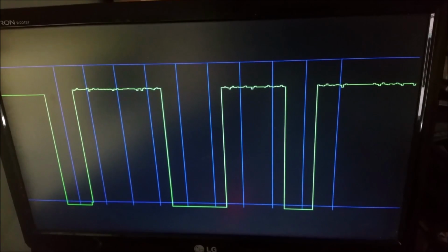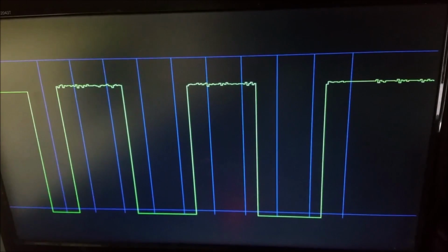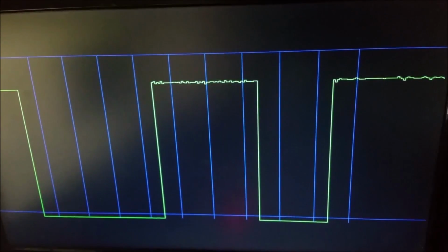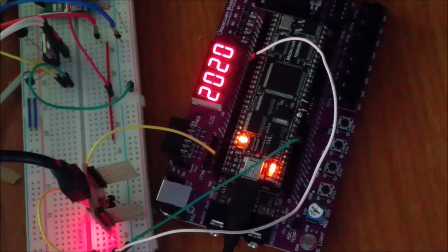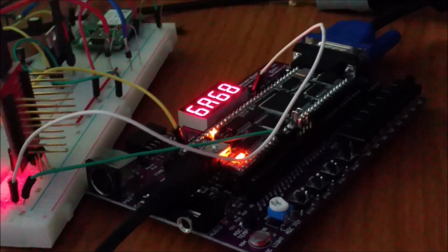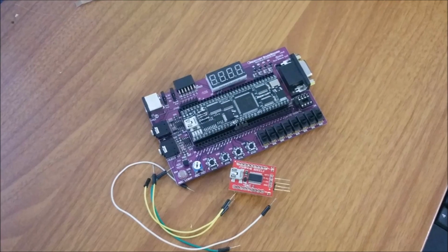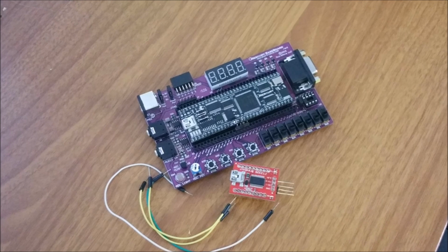In this video, we will be building our very own single-channel oscilloscope that will auto-trigger on incoming UART messages. The design will also interpret the waveform concurrently and display the ASCII values on the 7-segment displays. Surprisingly, this won't be as difficult as you might think. We'll be using the Mercury FPGA combined with the new baseboard and an FTDI breakout board.